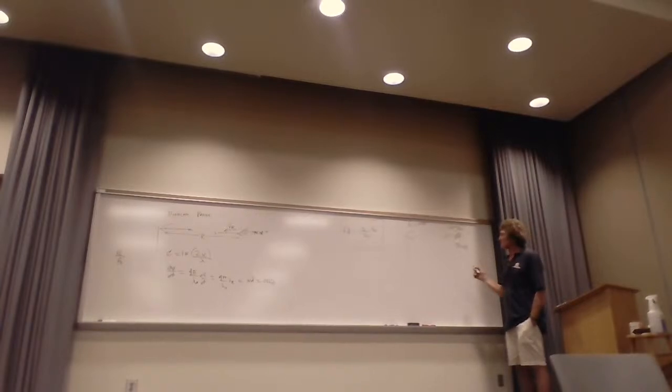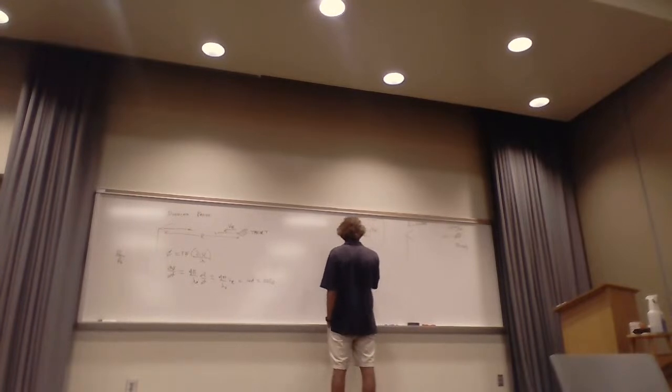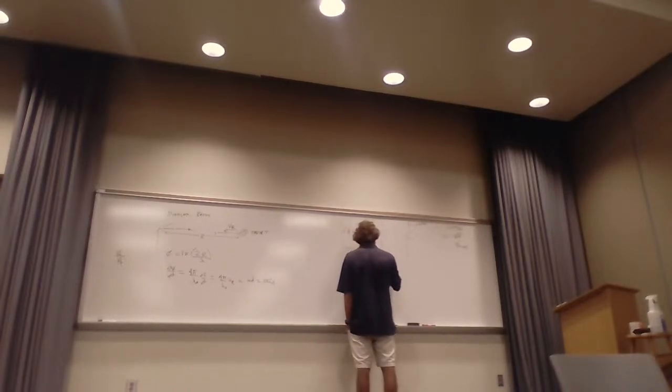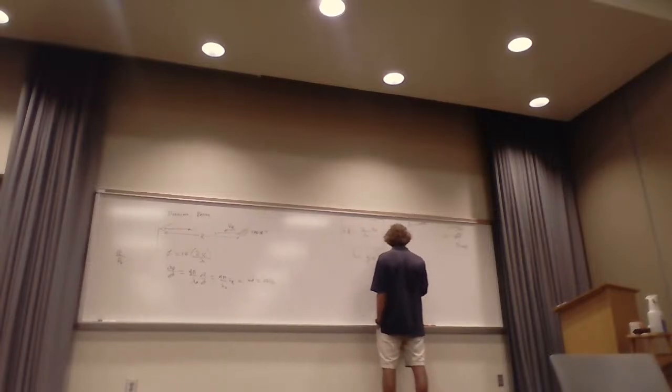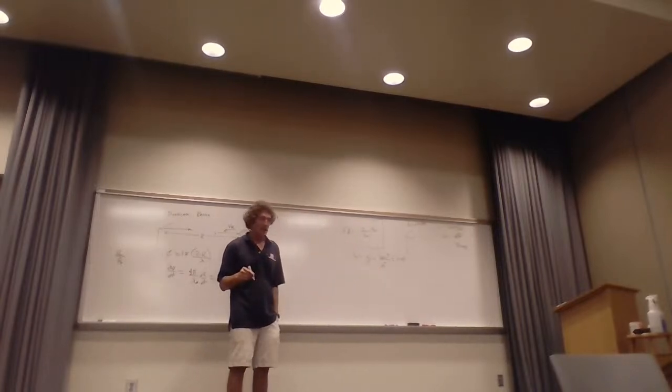All right, so that's 90 meters per second. Let's see what the shift is. Remember, it's a 10 gigahertz center frequency, all right? So here, first thing we need is lambda naught. Lambda naught is going to be C over F. F is 10 gigahertz, C is 3 times 10 to the 8th meters per second, divided by 10 gigahertz, which is 10 to the 10th. So that's 0.03 or 3 times 10 to the minus 2 meters, right?